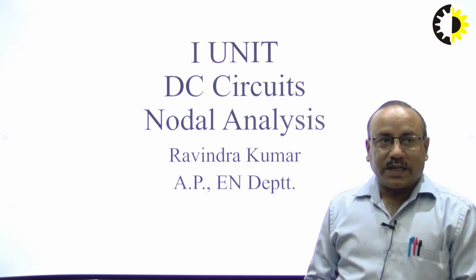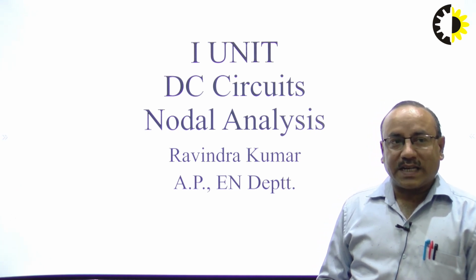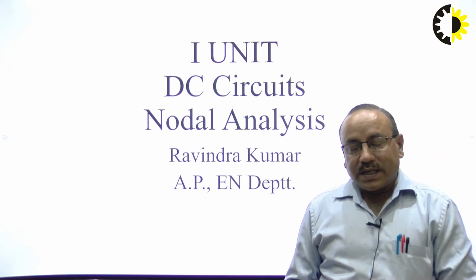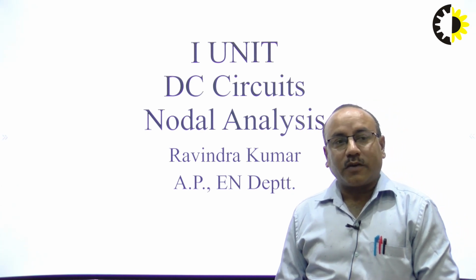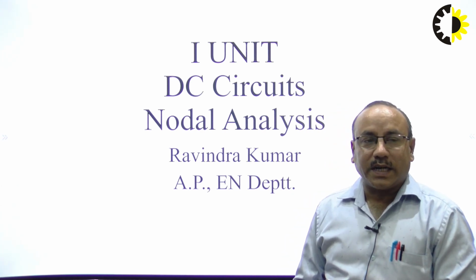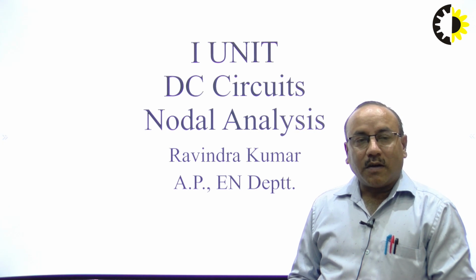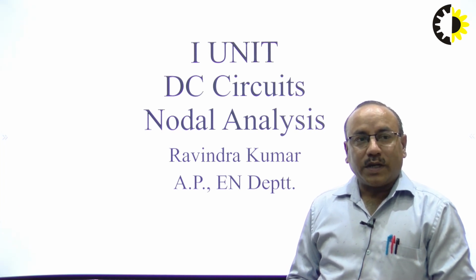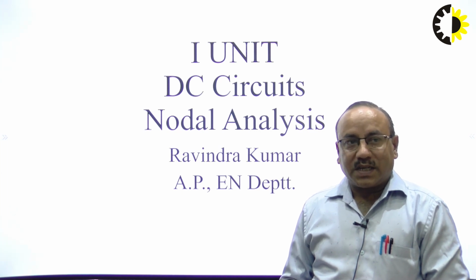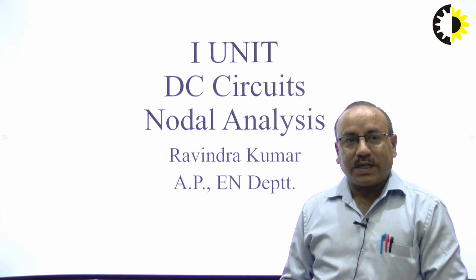So now the first thing is, why do we use this nodal analysis? As we have seen in the previous lecture, we have taken the mesh analysis or loop analysis for solving a circuit. Similarly, nodal analysis is used for solving a circuit. Solving means to simplify the circuit. That means with the help of it, we can find voltage in any branch or current in any branch, and also we can find power in any branch by use of this nodal analysis method applied to any circuit. So this is the basic idea about nodal analysis, why do we use it, and what is its purpose in a circuit.